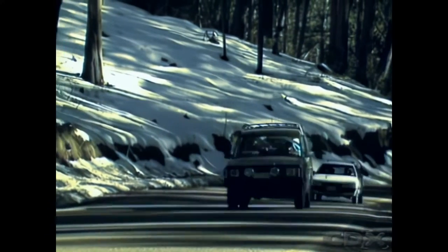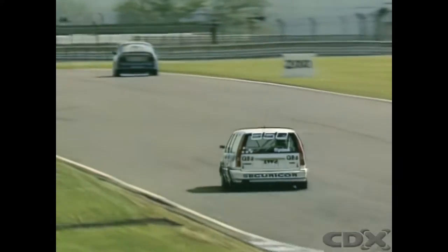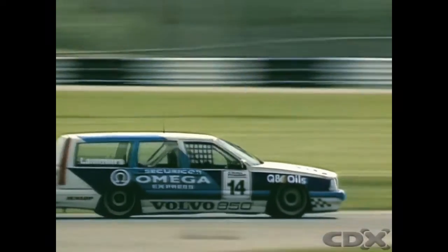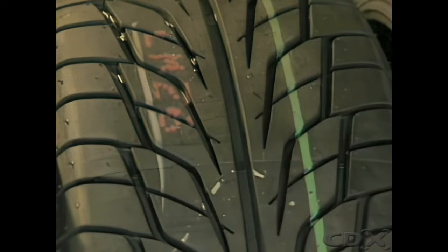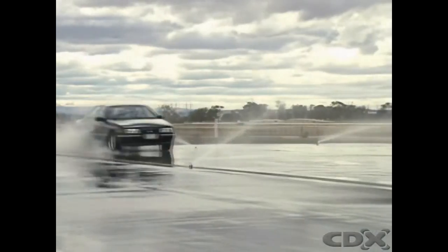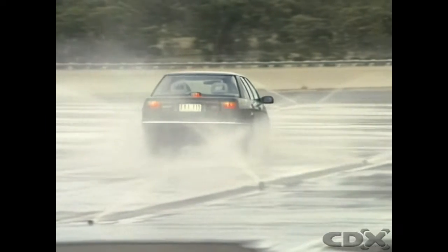Control of a vehicle in any weather conditions depends finally on frictional forces generated between the tires and road surface. On a dry road, a smooth rubber surface can provide a high coefficient of friction, sufficient to maintain a degree of control during braking, accelerating, and cornering. In wet conditions, the coefficient of friction between a smooth tire and the road surface falls to an extremely low value. Grooves in the tread pattern clear water away from the contact patch area. This allows a relatively dry area to be formed and for road adhesion to be maintained.